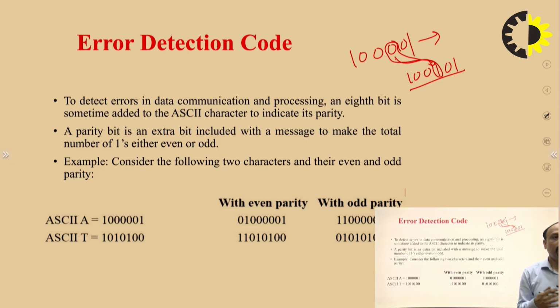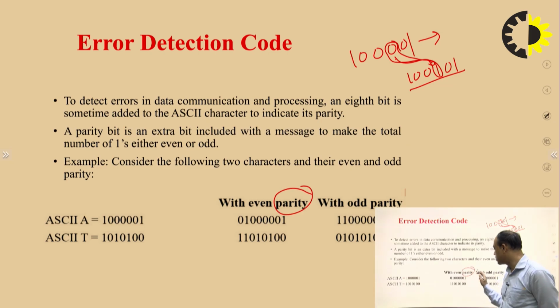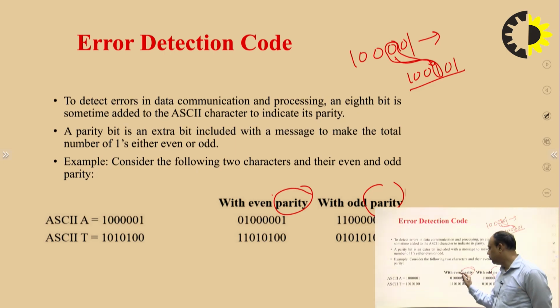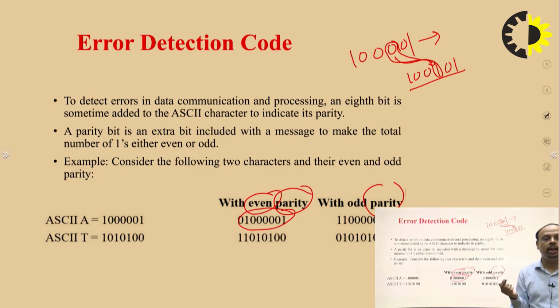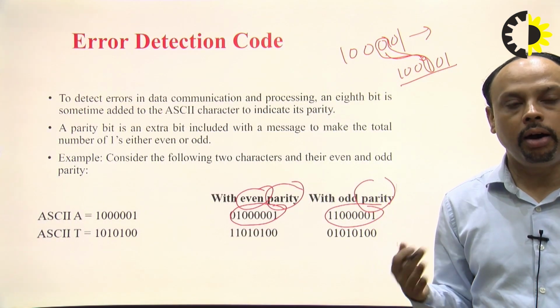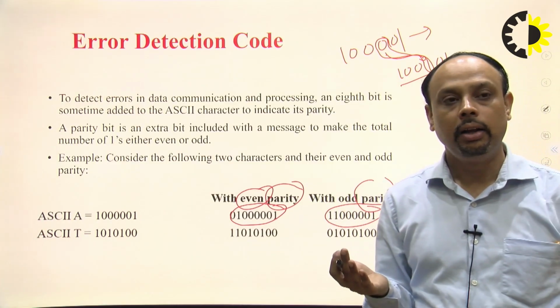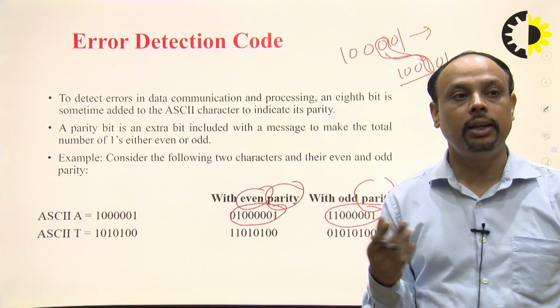For that, we use special parity bits between the main message bits to find out which bit has an error and how we are going to correct it. For even parity, we maintain an even number of 1s in the symbol, and for odd parity, we try to maintain an odd number of 1s in the given code by adding some extra parity bits.